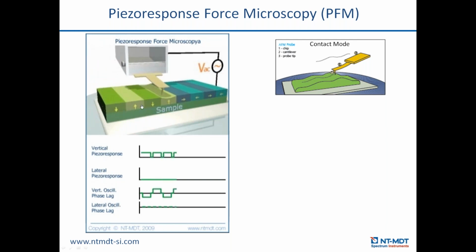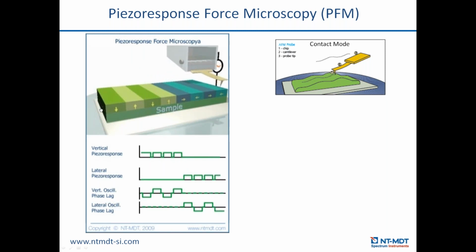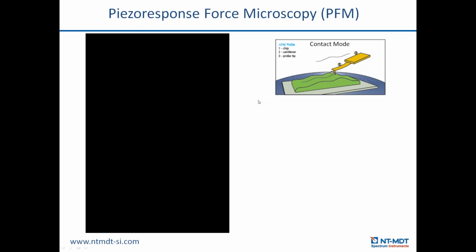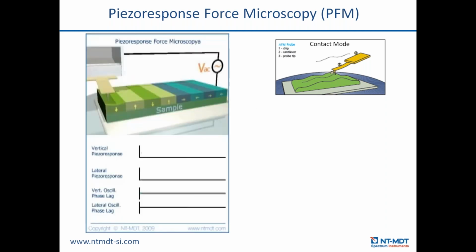We have the sample, we apply an alternating voltage, and when the tip goes along areas with different polarization, we get different amplitude and phase response. Thus, we can study the domain distribution in piezo materials.